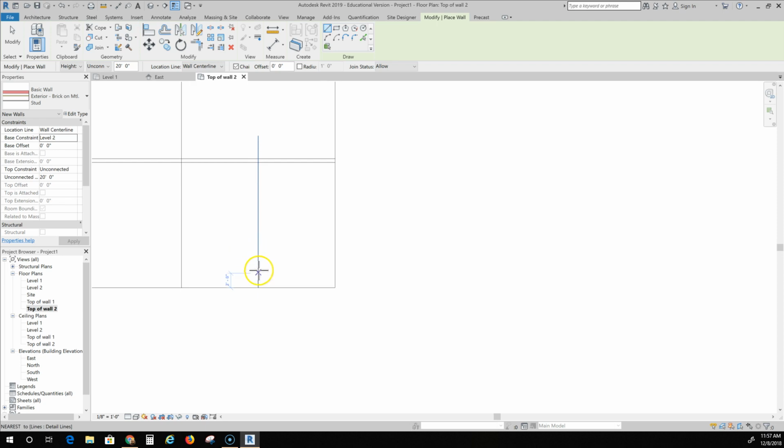Typically you'll move it back from the edge of the roof and back from the front walls. It's not 100% necessary to do that. If I had a wider overhang, like for a front porch or something like that, I could probably build it right on top of my bottom floor walls. And that's typically probably going to be the most desirable anyway. But I'm just showing you how to make a dormer. So I'm going to move it back about 2.5 feet from the edge.